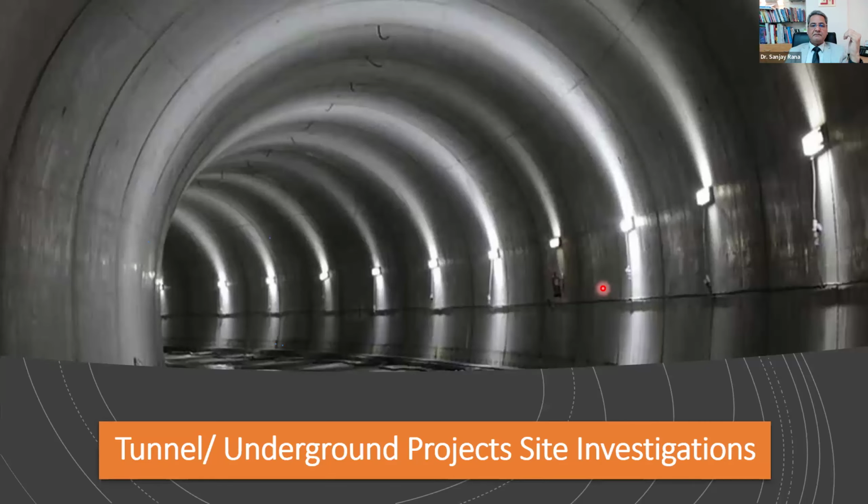It is all integrated. So geotechnical methods tell us what exactly is there, because they're very, very accurate. But they tell you only where you test, that is, only at that point where you do the drilling. Geophysics gives you continuous information, fills all the gaps, provides a broader picture, and you are able to target your boreholes more effectively. So together, they make a great combination. And ultimately, with this, you can avoid surprises during construction. Avoiding surprises basically means less cost overruns, less time overruns, etc.